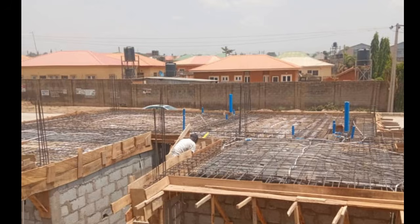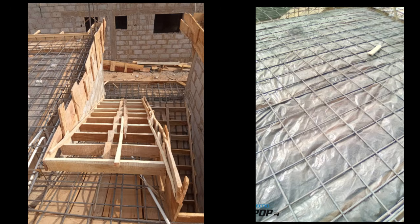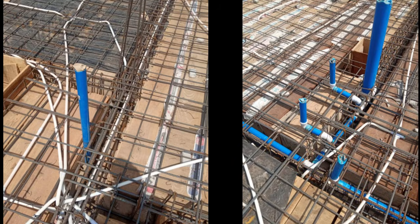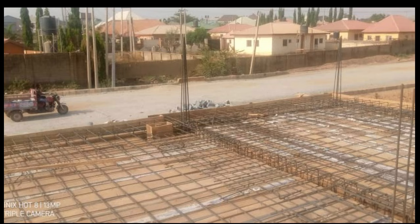This stage requires a lot of materials and a lot of workers. Planks and timber for decking formwork, bamboo to support the decking loads, reinforcement bars for slab and beams, plumbing and electrical pipes, cement, sand, gravel, and so on. As soon as all the preparatory work has been completed, inspection was carried out by the structural engineer as well as the mechanical and electrical engineers. Thereafter, concrete is mixed and poured over the deck area.